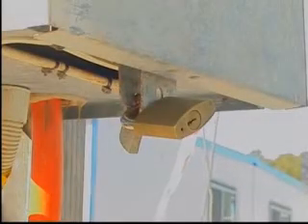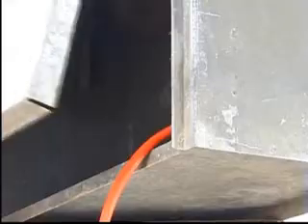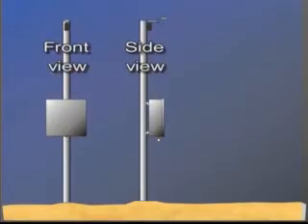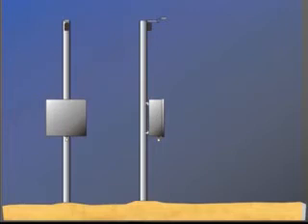Main switchboards are securely mounted on a temporary service pole firmly fixed in stable ground. Wet areas should be avoided by locating the pole in elevated, well-drained ground. Supply may be either underground or by aerial cable. The location of the pole should not obstruct on-site traffic or material storage.